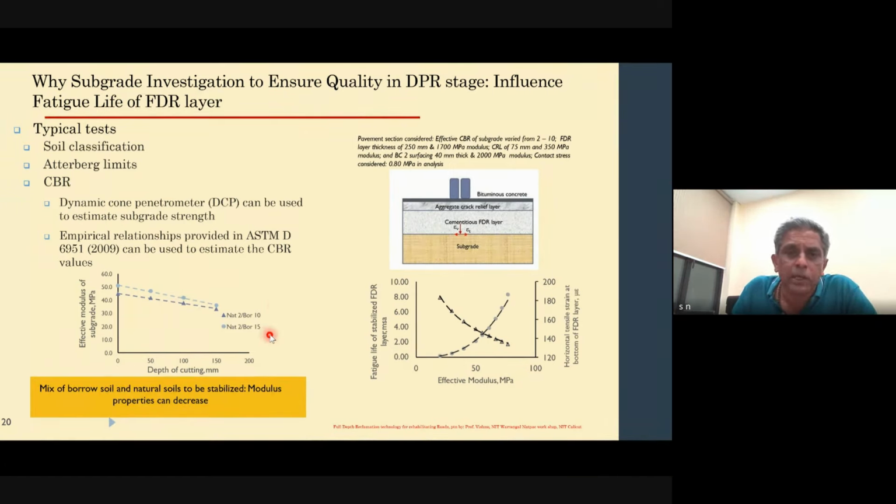Now, the durability test is typically not done on all the different cement proportions. The one that you get, which is your ideal mix, wherein you found the optimum cement content, that mix only needs to be tested for durability. Because you are finalizing that cement content and you are just checking if the durability criteria are also met for that particular mix.